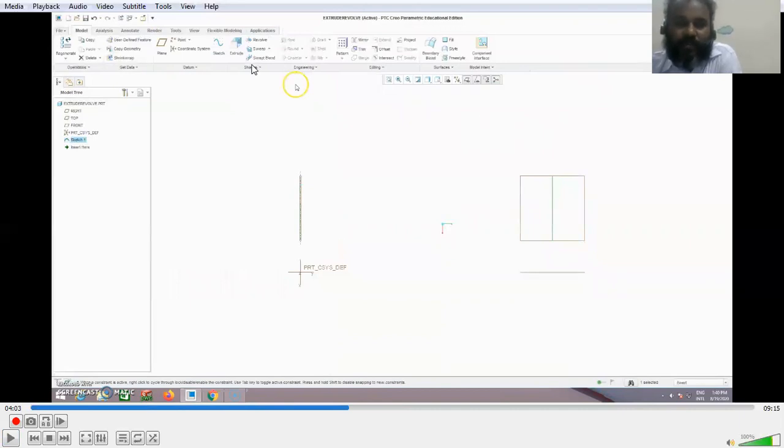So next what is to be done is, I'm going to use the revolve option. So this is the center line based on which I'm going to revolve this particular sketch that I created now. There is a straight line here. Though it appears like a square and a straight line, the square is just the plane in which I drew. So this is just the straight line which I'm going to revolve about this axis. So let us see how it turns out to be.